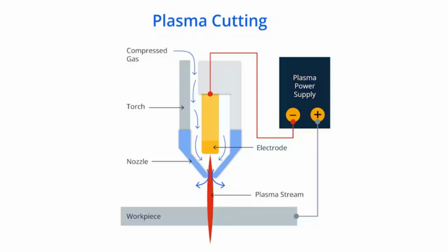In plasma cutting, gas is transformed into plasma when it is heated, which results in extremely high temperatures of up to 27,000 degrees Celsius being generated. The plasma arc cutting process severs metal by means of this highly constricted arc jet, which has sufficient energy and force not only to melt the metal, but also to eject the molten material. Because melting, rather than oxidation, produces the cut, plasma cutting can be used to cut any metallic material. It requires no preheat and produces minimal distortion in the material being cut.